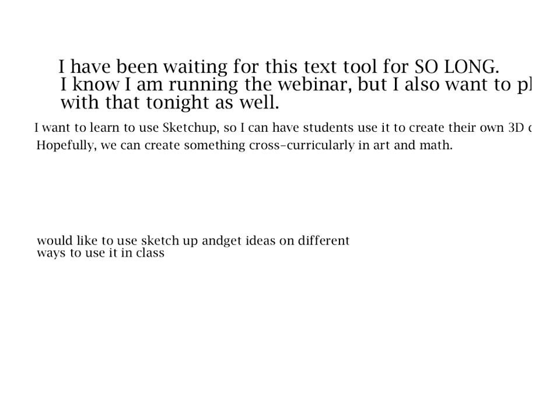To be honest, I would say to a certain degree, SketchUp is easier to work with. And the reason I say that is that Tinkercad is a program that uses something called primitives. So typically when you're designing a 3D model in Tinkercad, what you're actually doing is going to a little tool set on the side window and grabbing a 3D shape that's already been constructed and dropping it onto the screen. And then you get a little scale bar that allows you to change the width of that shape, the depth of the shape, the height of the shape.